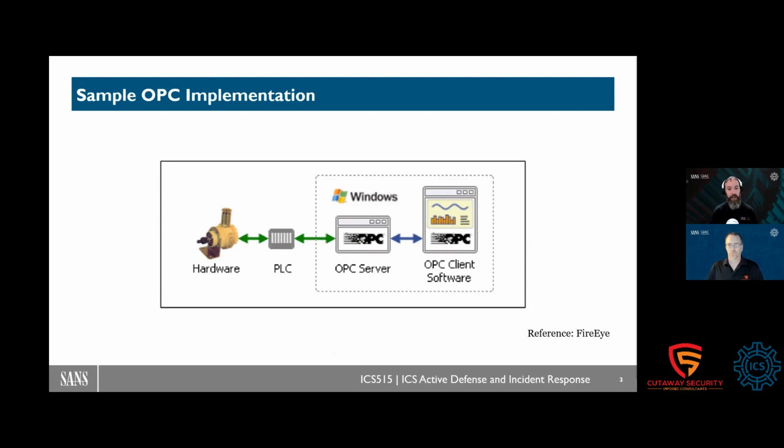And then we've got alarms and events, where we're looking at a process alarm, like our 62682 style alarming for high level and plant trip and things like that. So there's a few different ways you can slice and dice how OPC is getting data out of the environment.